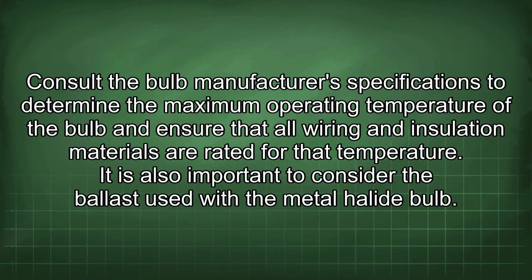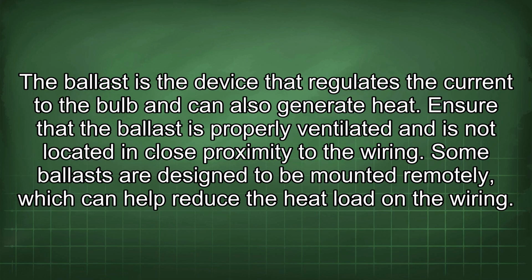It is also important to consider the ballast used with the metal halide bulb. The ballast is a device that regulates the current to the bulb and can also generate heat. Ensure that the ballast is properly ventilated and is not located in close proximity to the wiring.